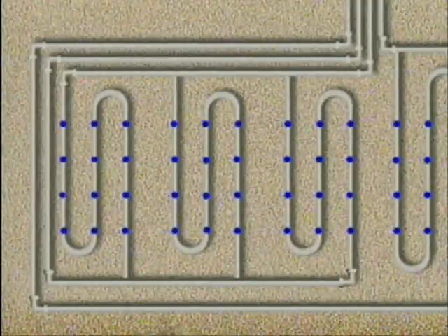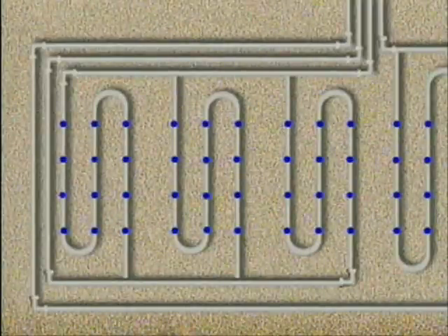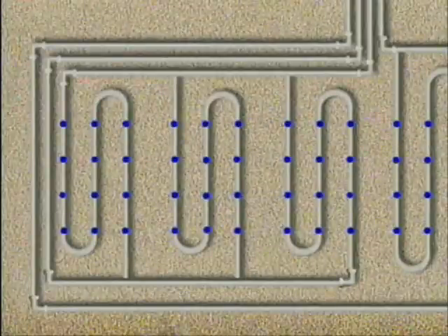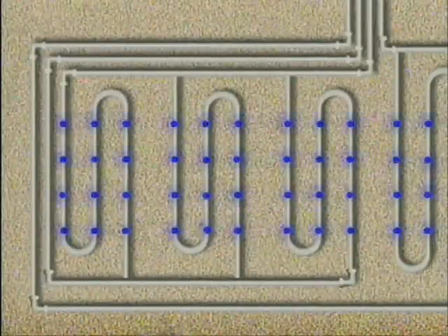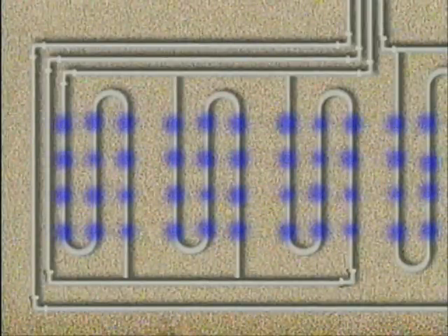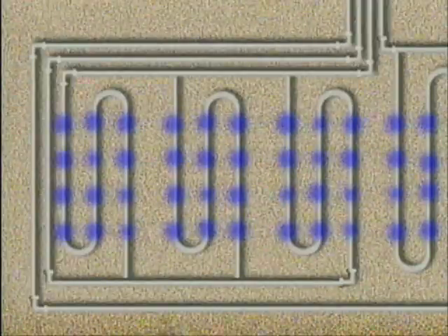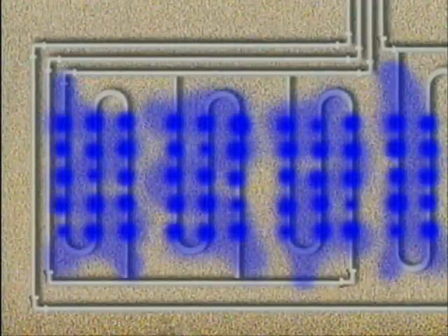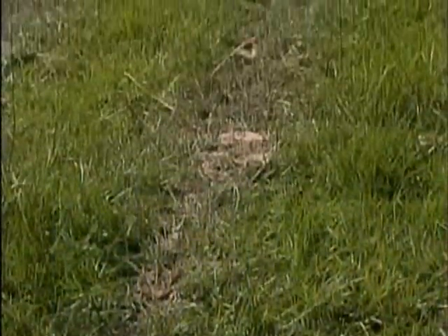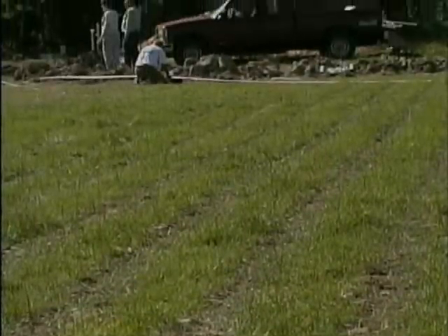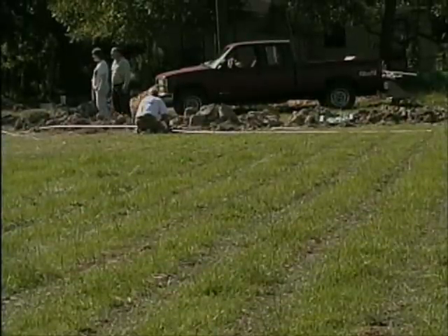Emitters are placed in the drip tubing every 12, 18, or 24 inches. This forms a grid pattern for application of the wastewater into the soil. For a drip field to remain unsaturated, emitters and laterals must be spaced properly. If they are too close together, problems can occur. If your field area is restricted within the landscape, you may opt to have multiple fields or zones.